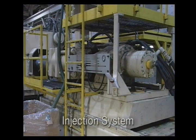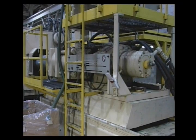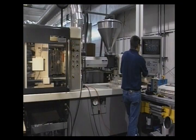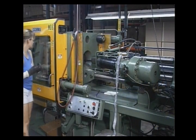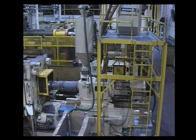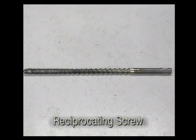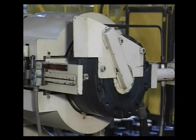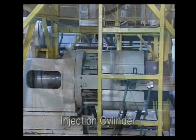The injection system heats the thermoplastic material to its appropriate viscosity or flowability and then forcefully injects it into the mold. There are 2 types of injection mechanisms: the reciprocating screw, which is the most common, and the 2-stage screw. The main parts of the reciprocating screw injection system are the hopper, a reciprocating screw inside an externally heated injection barrel, a hydraulic motor, and an injection cylinder.